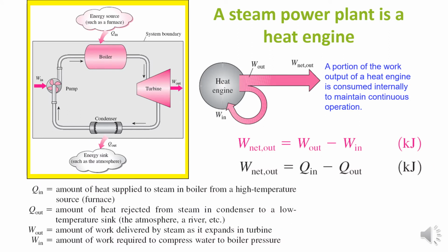Okay, we can look inside the heat engine, which has a boiler, turbine, condenser, and pump. If you remember when I was explaining about the aircon, or the chiller system, it also has most of these components, but an air conditioner won't have a turbine, and the pump is usually replaced by a compressor.